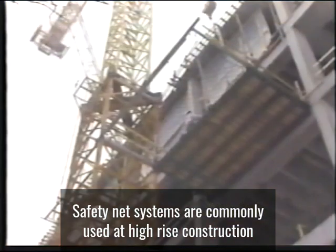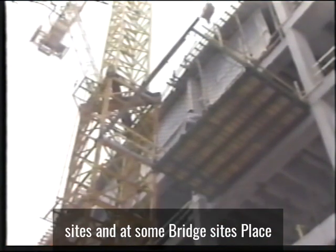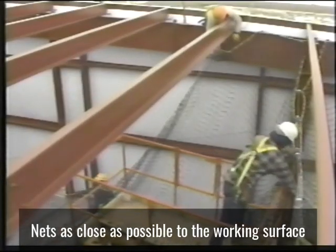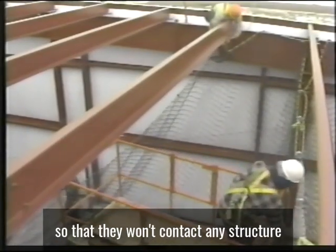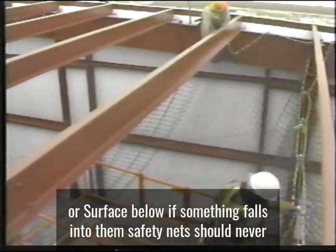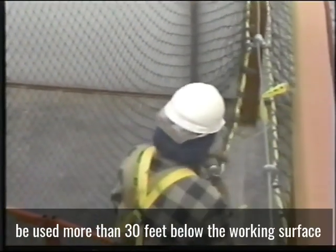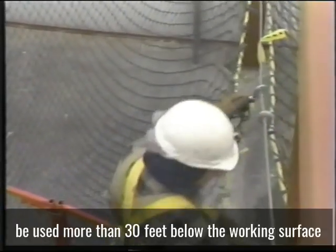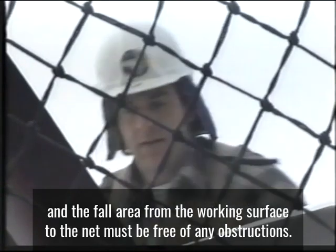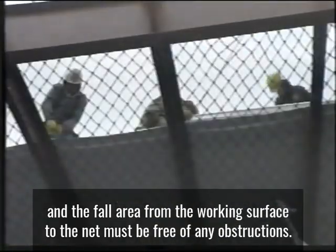Safety net systems are commonly used at high-rise construction sites and at some bridge sites. Place nets as close as possible to the working surface so that they won't contact any structure or surface below if something falls into them. Safety nets should never be used more than 30 feet below the working surface. And the fall area from the working surface to the net must be free of any obstructions.